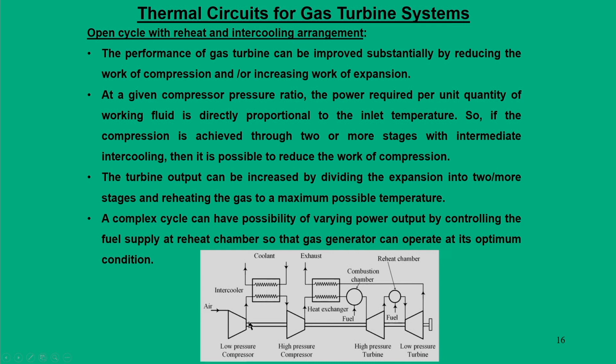From the first stage compressor, the pressure goes up, and the temperature also goes up, but what we require is to bring this temperature back to the atmospheric or ambient conditions. So, the intercooler does not do anything to the pressure, rather it brings the temperature back down to normal conditions.